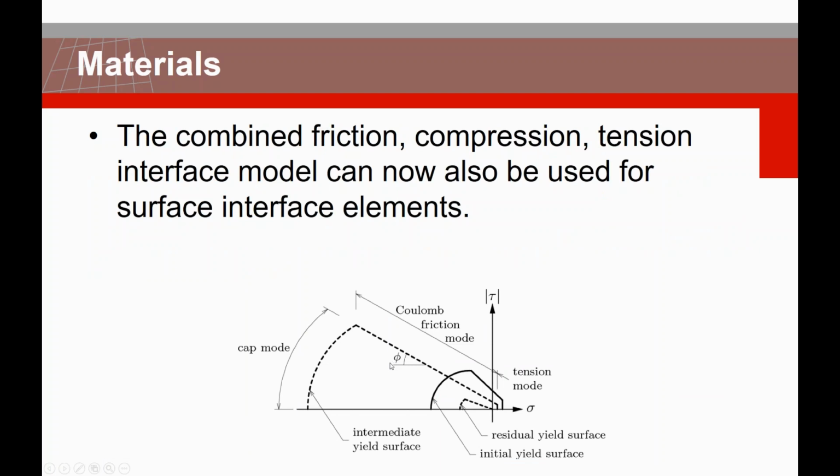We have made a 2D interface related to cracking, shearing, and crushing interface that we had for masonry structures. And this one initially was for shell elements as a 3D and basically plane stress. So it was kind of a 1D line. Now you can model that based on the surface, and you can incorporate it between the solid blocks of masonry.